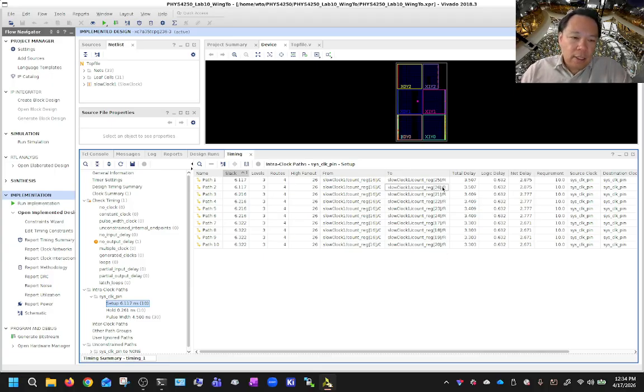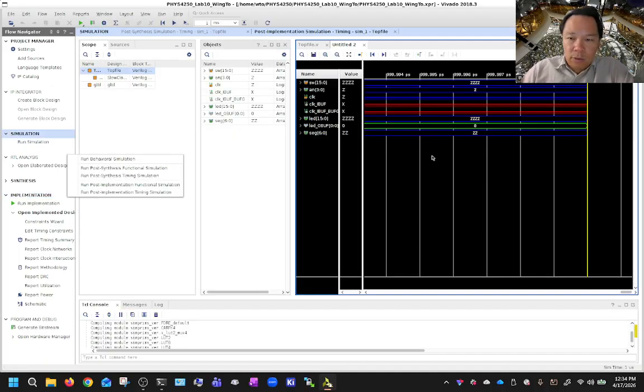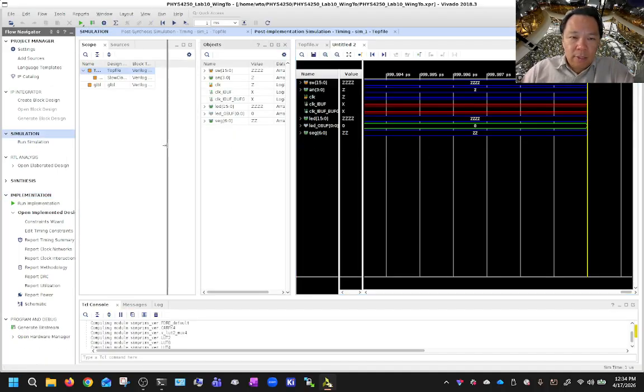You can design things to minimize that, to make things go faster and faster, but for our application, just don't do anything less than 10 nanoseconds. You can run this report and make sure things actually operate correctly within that 100 megahertz clock that you're using. If you can't, then you have to slow down your clock to make sure the logic still flows through without creating errors. So that's how you play with both the timing report and, more importantly, these timing diagrams.